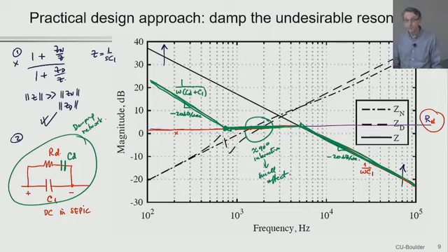So as you look into the assignment, you will see that you can exploit this discussion here to your advantage. First of all, you want to find out what RD should be placed so that you have the desired interaction between the extra impedance and the ZD and ZN. Then you decide how large CD should be placed so that you have this nice range of frequencies right here where that interaction is, well, the impedance looks resistive. That's it.